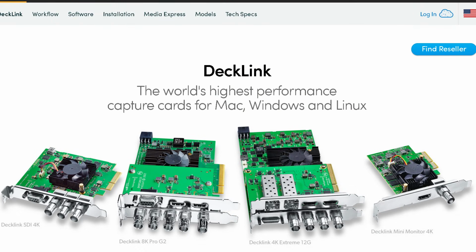Many higher end capture cards, especially the PCI ones that you're slotting into the motherboard, will often have a number of different ports that you can switch between being either input or output. And those are really great in higher end production scenarios where you have several incoming camera feeds that are plugged in via SDI and then an LED wall. And like all of that can be running through specialized output hardware. These devices are also critical if you need gen lock, which is mostly relevant if you're dealing with high grade production hardware for film shoots or dealing with large LED walls.